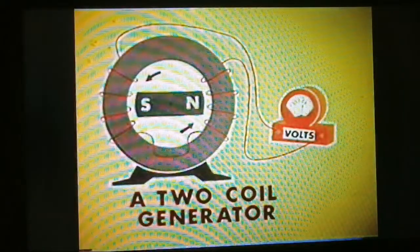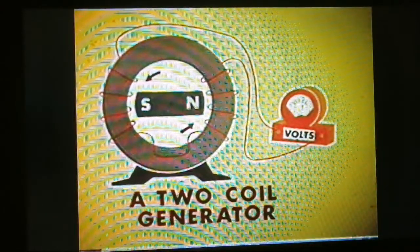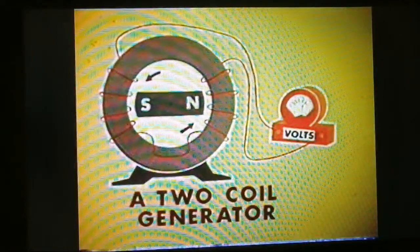A second coil placed opposite the first will produce voltage. By winding this second coil in the opposite direction from the first, both coils will produce identical voltage even though they're affected by opposite poles of the rotating magnet. Instead of two circuits with identical voltages, we'll tie the second coil in series with the first. Now, instead of two separate circuits of equal voltage, there's just one circuit with twice the original voltage.